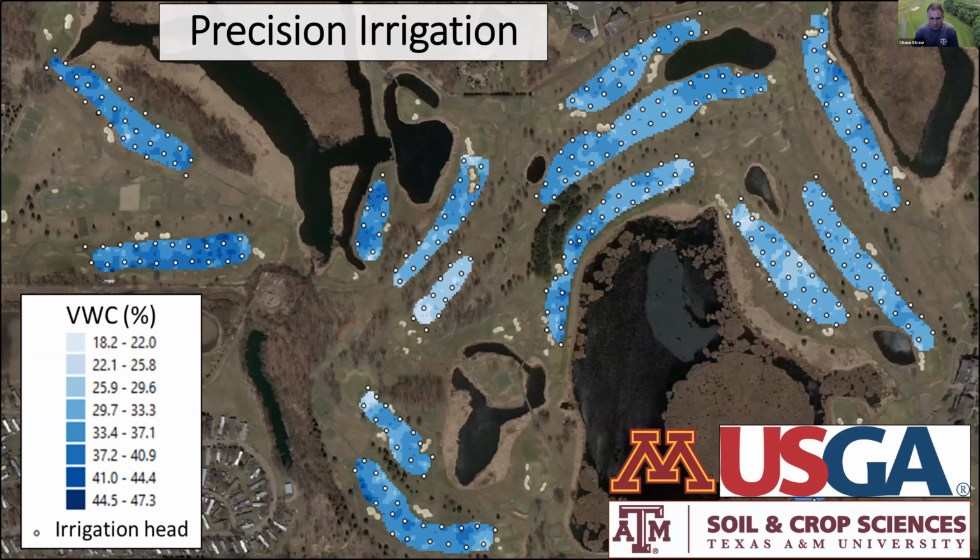So if you time it right, if you collect your data, and this is based on our experience, there's no formal study that's been done, but I've collected data on a lot of golf courses over multiple months, and the wet areas do not typically change from month to month. Even with the courses we've done year to year, wet areas are typically the wet areas, dry areas are typically the dry areas. Now, with that said, there can be some small variations, but that's just generally speaking. So if you go out and collect your data after a uniform rainfall near field capacity, then you can have a soil moisture map that looks similar to this.